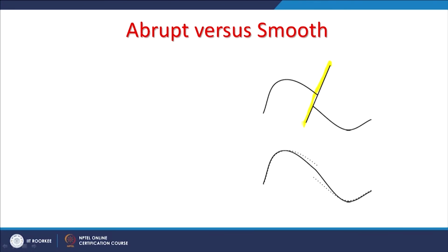Or there may be a geological dike, or maybe a quartz reef, or a geological fault, and therefore abrupt changes will occur in my surface instead of a smooth surface, because all natural phenomena are not represented in a smooth fashion, there might be abrupt changes. So, abrupt interpolators allow for barriers which we can use in interpolations, whereas smooth interpolators produce a smooth surface.